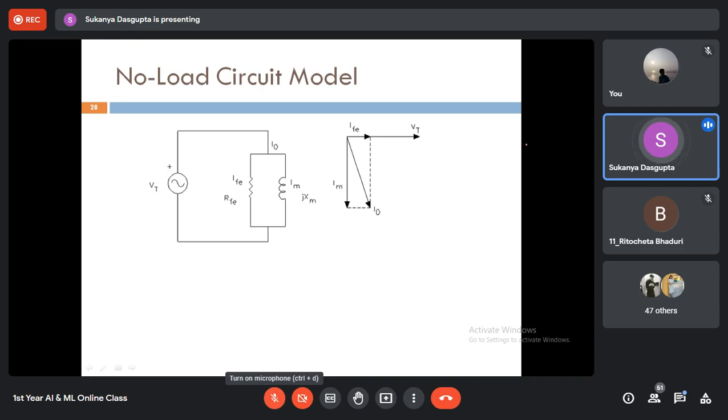When the supply is connected with the primary side and the secondary side is left open, then a huge amount of voltage can be generated at the secondary terminal, at the secondary winding, right? Because the transformer operation is going on. The core is magnetized. The supply is still on. So primary current is flowing. So EMF will be induced at the primary winding, right? And this EMF induced at the primary will develop more EMF at the secondary winding. And imagine the secondary side is not connected to any load. Then what will happen?